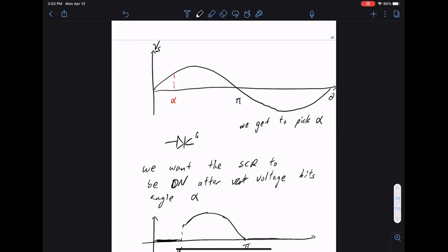I'm confused about the turn on voltage because you said we need to send a current pulse in order to turn on the gate, but that it also gets tripped by the turn on voltage. Is the turn on voltage the voltage drop across the SCR while it's building up? And if so, wouldn't that automatically hit a point as the current keeps going through it, and therefore it's going to drop more voltage until a certain point?